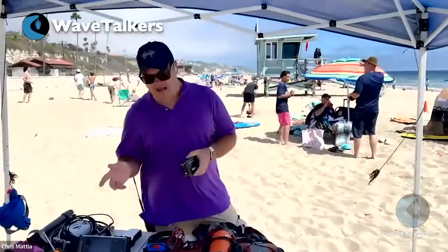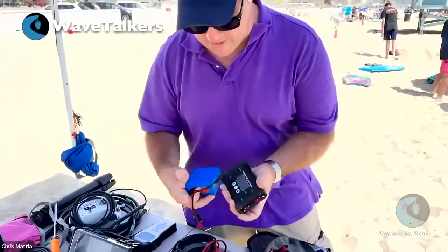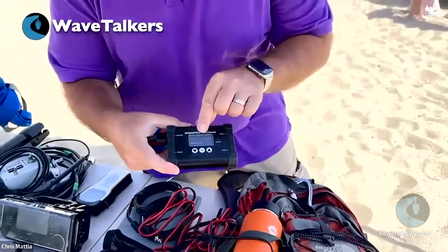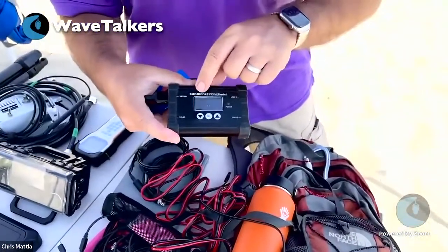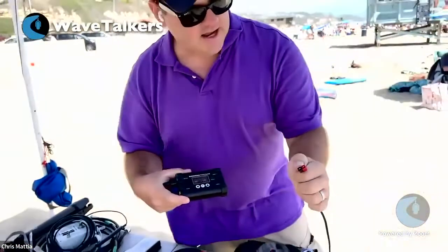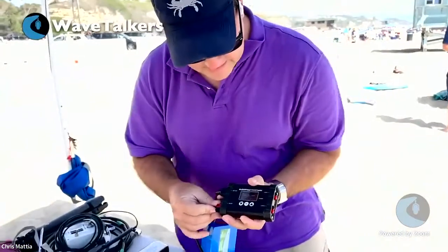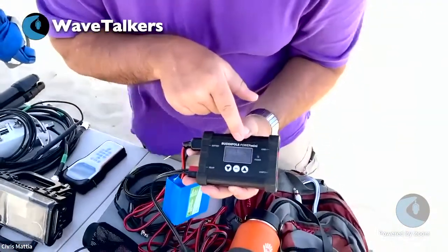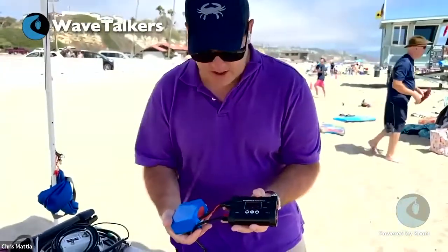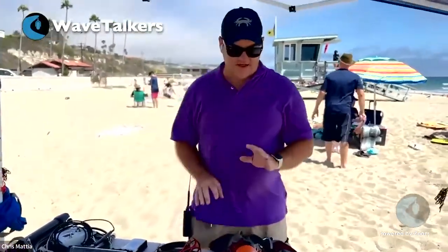All right, so now we're going to get the solar panel running up on charge here. So we've got our Bioenno 3 amp hour battery, and all you need to do is plug that into the battery port on the Power Mini. You can see the little LED just lights up, and so we've got power going in. So this is operating, ready to go at this point. Then we'll take the line coming from the PowerFilm Solar and plug that into the solar charging port. And look at that, we have power coming in. We're generating 2.75, 2.8 amps of power just off of that little small panel. So we'll just leave that there, and the battery is being topped up.